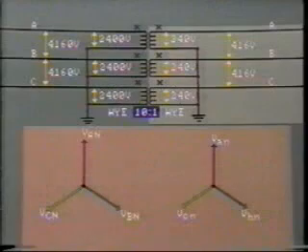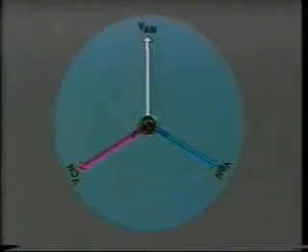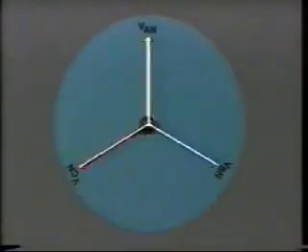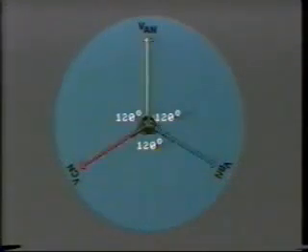In the last segment, during our discussion on polarity, we looked at the voltage relationships between three interconnected single-phase transformers. You'll remember this circuit diagram, but in order to understand this, it was necessary to also study the diagrammatic representation of the phase relationships between the various voltages on both primary and secondary side. This diagram is known as a phasor diagram. It shows the magnitude and the phase relationship between the various voltages in the system. This is for a fixed moment, an instant in time.